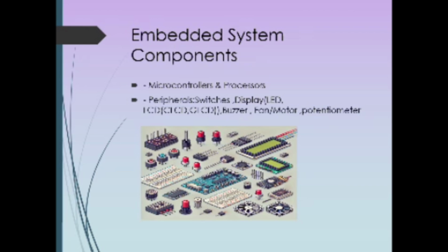Pin 4 of LCD is RS, which is the register select pin, used to toggle between command and data register. Fifth is the RW pin, which is used to toggle the display between read and write operation. If R mode is selected, then the data passed to the LCD will be displayed or will be only readable. If W is there, then we can change the data given to the LCD. E pin is the enable pin, which acts like a switch. Pin 7 to pin 14 are data pins used to send data to the display. Pin 15 and pin 16 are connected to plus 5 volt and ground.